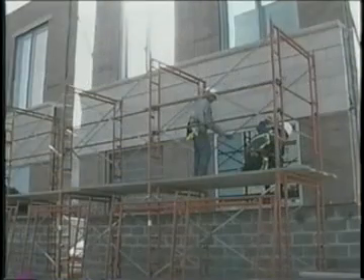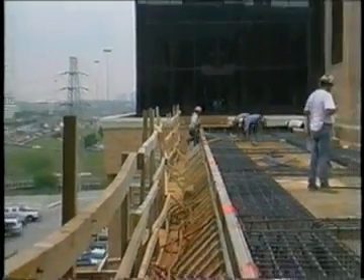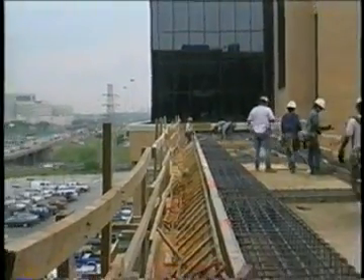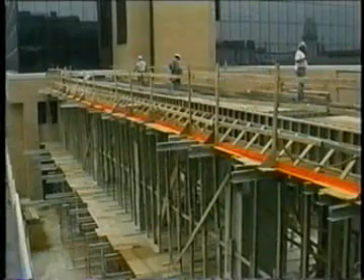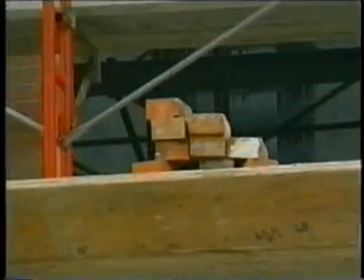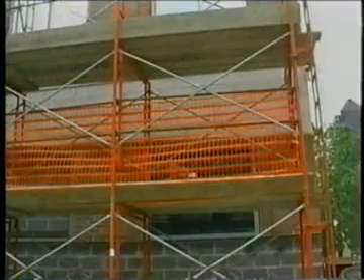Whenever the hazard of falling objects exists, guardrails shall have openings that are small enough to prevent the passage of objects to lower levels. Install a solid panel or screening barrier in the guardrail system. When tools, equipment, or materials are piled higher than the top edge of the toe board, paneling or screening shall be used from the walking or working surface up to the mid-rail or top rail as appropriate.